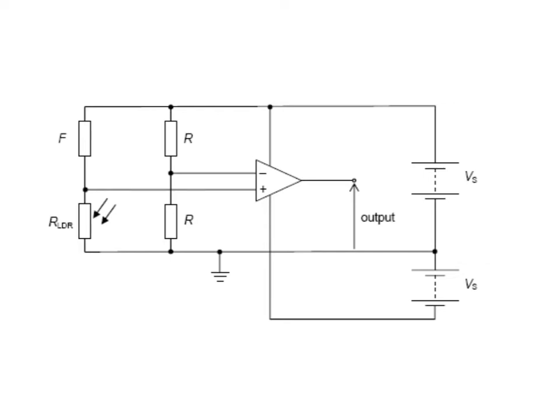Now let me give you an example of how to connect your circuit to set up your op-amp as a comparator. Remember that the op-amp must have similar supplies for positive and negative, similar values. If it's positive 9, it's negative 9; positive 15, negative 15, remember? These are supply voltages, right? So how do you connect your circuit to give you identical values, but one positive, one negative?